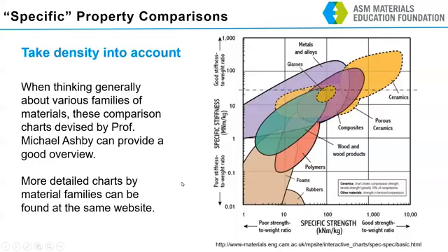So this gives me a way to plot the behavior of a wide range of materials while I take the mass into account. So normally in a design situation, I would have a specified strength requirement that I have to meet, and I would be interested in how much movement there was associated with that force. That's like the 100-kilogram person walking out on the diving board, and we're only allowed to flex 1 centimeter. Or I would have an allowable amount of flex, because most of our parts are not used all by themselves. They're next to some other part, and they can only flex so much before they'll run into something and cause a failure. So in that case, I would be looking at how much force is required to stay below that deflection limit.